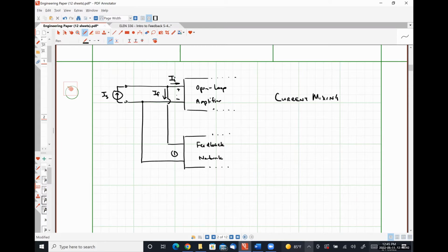And then here is our voltage VI for the input terminals of our amplifier. And in such a configuration, we find that our input resistance with feedback is made smaller, so that we'll have Ri over 1 plus Ka.